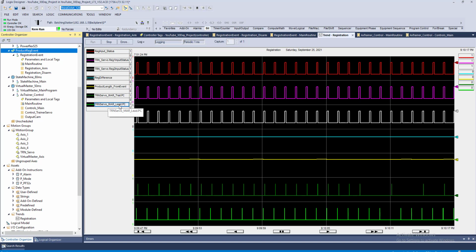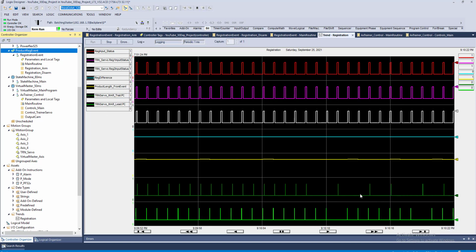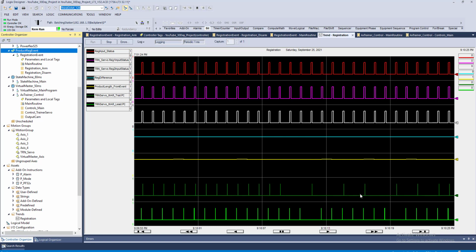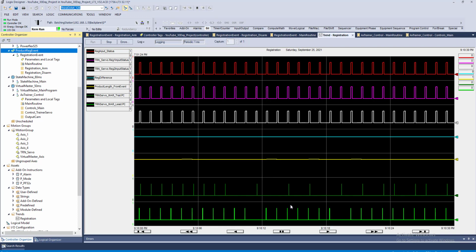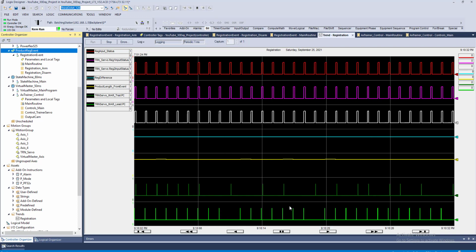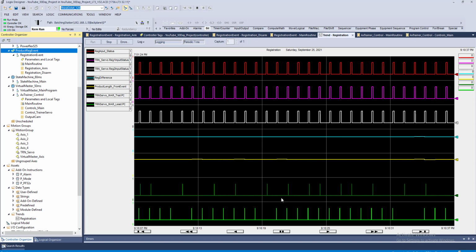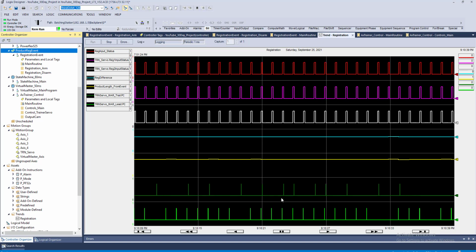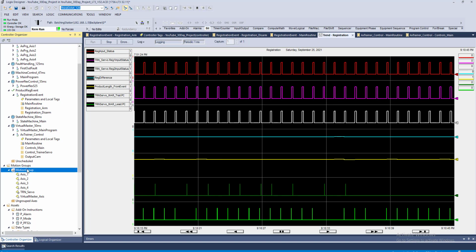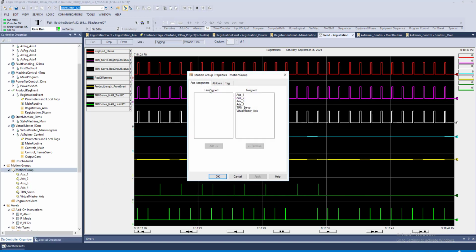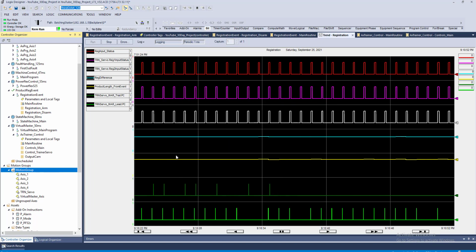You see that the PC bits change a little bit. Again, this data is not really reliable because you cannot scan it as quick as it needs to be scanned. You would actually need to scan this in real time, and it needs to take precedence over what is called the actual scan rate and the way that scans are done. Keep in mind, motion is updated in this process every 4 milliseconds, and that's taking precedence over everything.